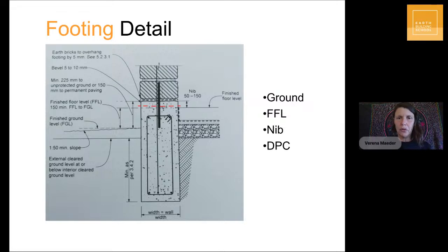During construction, when you don't have a roof on and it rains, it is to prevent rain that sits inside on your concrete pad or your floor from wicking into the bottom of the wall. And it is also in use, in case you ever have a burst pipe or something, so that there's no risk of water ever penetrating into the base of your wall.